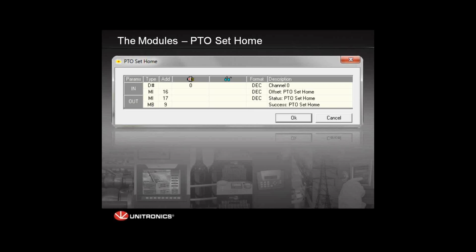If we're using absolute movement, we want to set the 0 point of the movement, and all the points and positions that we set from then on will be related to the home, to the 0 point of the movement. Then after we set the 0 point, we can tell the motor to get to position 100 or position 1000, and it will know where to go related to this 0 point.